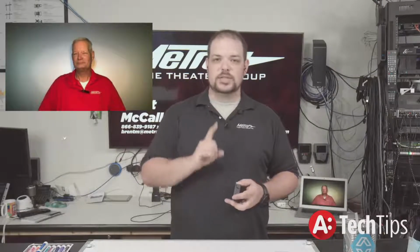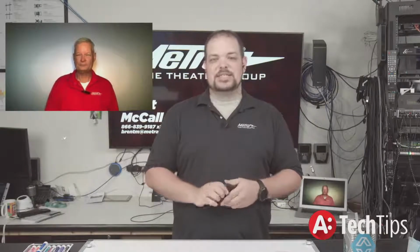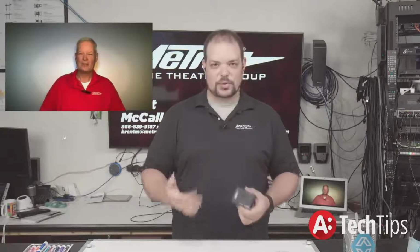If you have this problem, do us a favor. First thing is to go into the TV and turn off CEC. What happens is that this device has CEC capabilities. The display tells it to turn off, but it never tells it to turn back on, and so it stays off at that point. As soon as you turn off CEC, everything should begin to work correctly. And that was our fault. We specifically designed CEC into it and then forgot it.